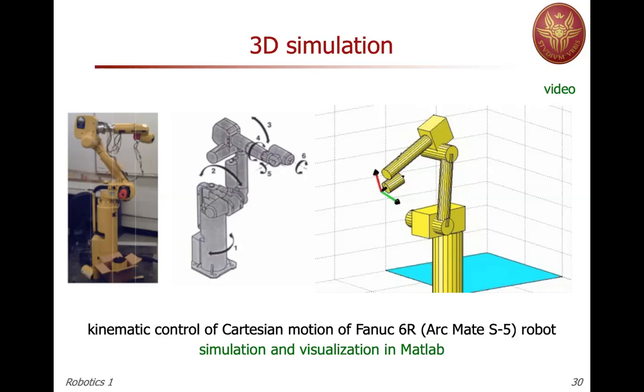In fact, in this simulation, there were no feed-forward terms. So only the error was driving the motion. The robot was starting from the beginning, from this position and orientation, and now it sees only an error getting to the final position and orientation. And because we have control in the Cartesian space, it goes along the straight line direction. There was an error only in, let's say, the z and y coordinates, no error on the x. So on the x, there's no error at all.